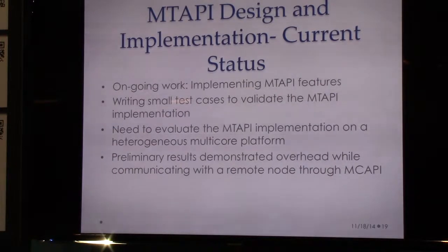The ongoing work right now is, the MCAPI design is out, the APIs are out, and we are creating an implementation. Siemens, which was also involved, they were the lead in coming up with the API for task management, have also put out an open source implementation just about last month. I think it's available for download. We are also working on creating the implementation for MCAPI, which is the tasks that I was talking to you about. The goal is to evaluate an MCAPI implementation on a heterogeneous multi-core platform.